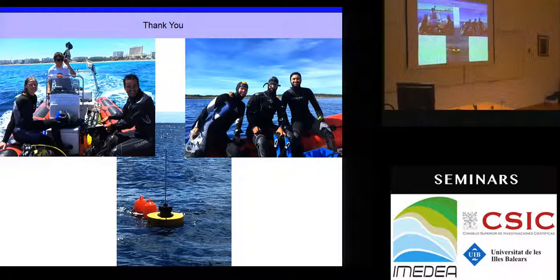So why would you use Delft3D instead of the XBeach model? Well, it really depends on what you're looking at. Let me start with the scenario where you're interested, for example, in the transport of pollutants or material or larvae or plankton. In that case, you probably want something that resolves the vertical structure of the flow, because depending on where the pollutants are, you get different transports. So in that scenario, I would definitely choose a 3D model like ROMS or Delft3D, because XBeach will not give you the vertical distribution of the flow.